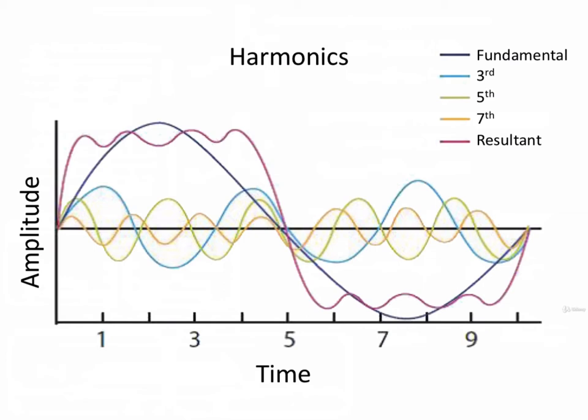When a non-linear load, such as a rectifier, is connected to the system, it draws a current that is not necessarily sinusoidal. The current waveform can become quite complex depending on the type of load and its interaction with other components in the system. All waveforms, no matter how complex, as long as they are repetitive, can be broken down into the sum of the fundamental sinusoidal wave plus multiples or harmonics of the fundamental frequency.